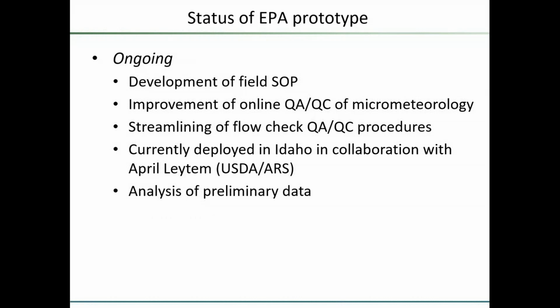So while we're monitoring the pressures on the critical orifice system and monitoring the flow rates in real time, part of the QA/QC is that when you go to exchange these samplers every week or 2 weeks, you directly measure the flows at the inlet with a NIST-traceable flow meter or flow device so that you can, again, double check the flow rates, because knowing the total volumes sampled during the deployment period is obviously a critical piece of information that you need to know. So we're doing some work there.